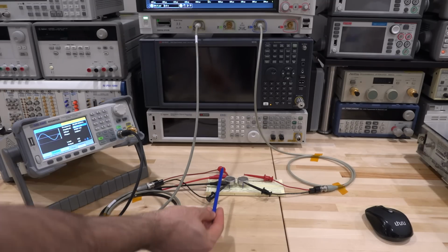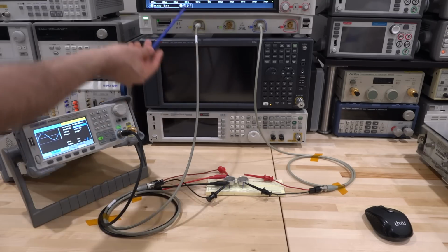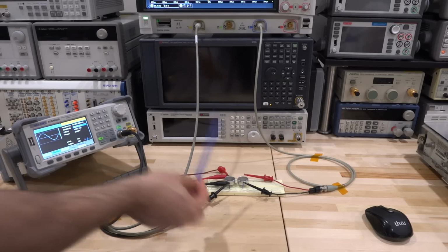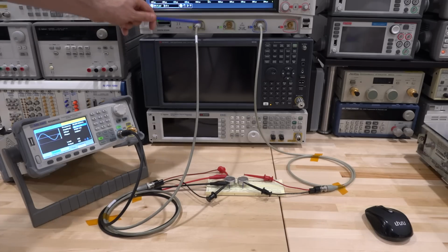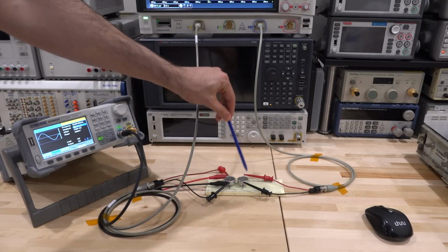At the same time, I'm looking at the signal in parallel to the first transducer, and I'm putting that on channel 1 of my oscilloscope. So 20 volts peak to peak at 25 kilohertz is being applied here, and it's being simultaneously monitored on channel 1. On channel 3 of the scope, I'm looking at the signal on the transducer on the right side.